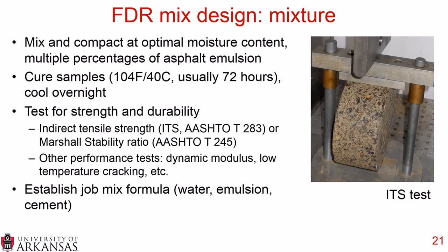So similar to asphalt concrete, you find the optimal amount of asphalt emulsion to add based on maximum strength and durability, and you can then establish a job mix formula. So you have your optimal water content, your optimal emulsion content, and your optimal cement content.